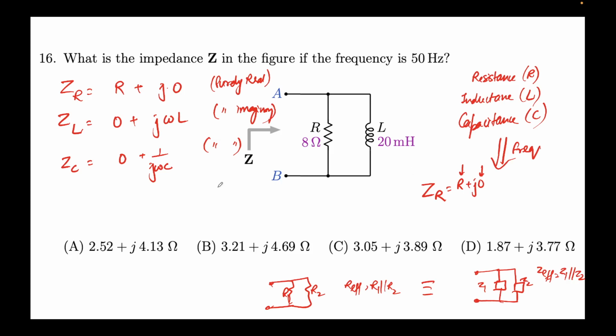All the analysis, the Thevenin, Norton analysis, and the nodal analysis that we had discussed for resistors become applicable. There the signals were not time varying. The signals were DC signals, they were constant over time. They may be pulsing, but they were not sinusoidally varying. There's no frequency associated with them. In this case, if we come to the frequency domain, and if we introduce L and C, then you will encounter differential equations which analytically are difficult to solve, right?